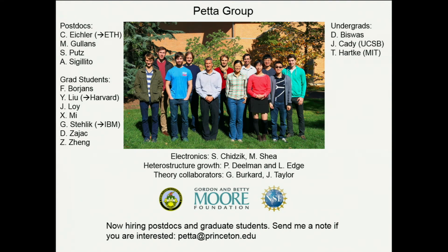I think that donors are really good for single qubits, but they're so small that if you want to have nearest neighbor exchange coupling, then you need control of matter at an atomic scale. And that can only really be done with STM, by building devices from the ground up. Donors are great for single qubits, just like NDs are really good for single qubits, but going beyond single qubits, we need a way that we can lithographically make things on a meaningful length scale, and that means tens of nanometers. Therefore, I'm down on donors long term. I think they're nice for some things, but I don't see them scaling well.